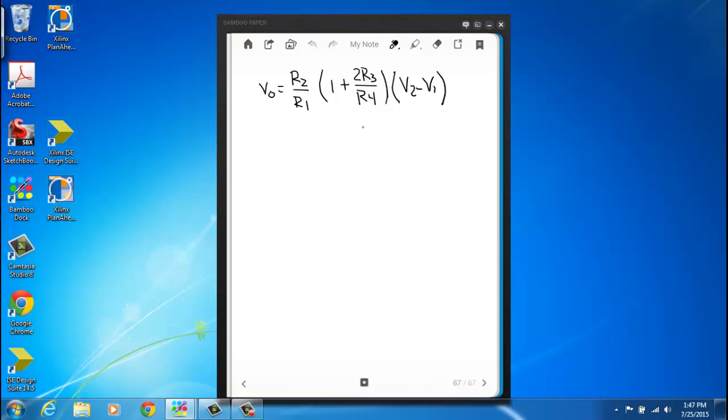Now, often with these types of op-amp circuits, the instrumentation amplifiers, the resistance values are made equal, so R1 is made equal to R2, which is made equal to R3, which is some R. And then also R4 a lot of times is a variable resistor that's labeled R gain, often a variable resistance like a rheostat.